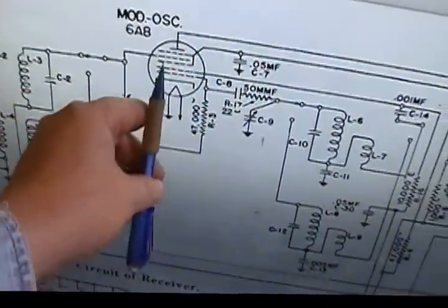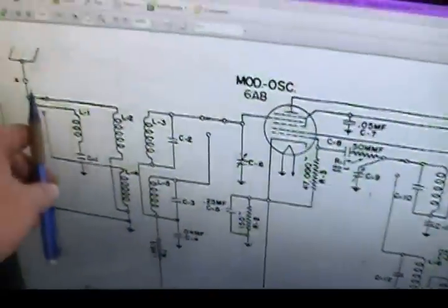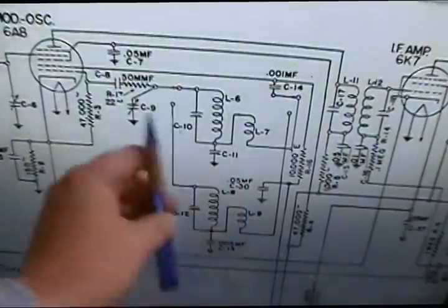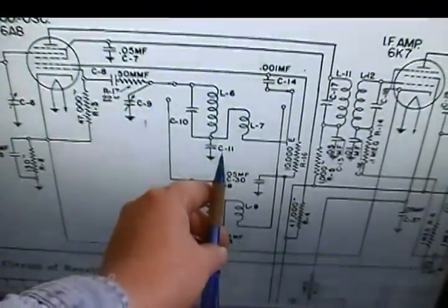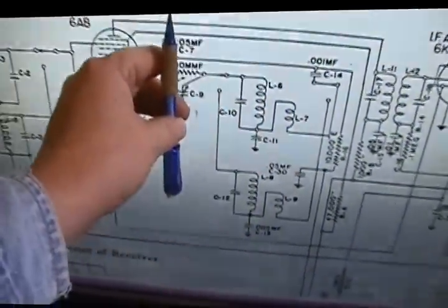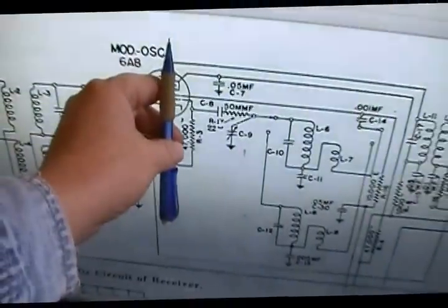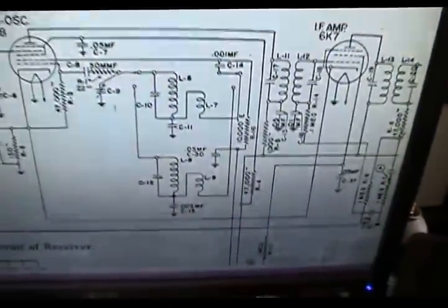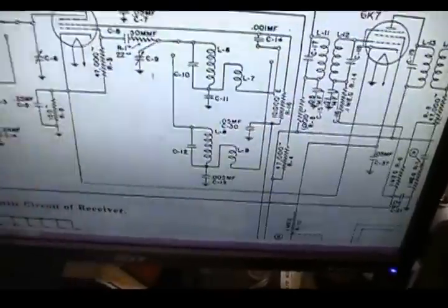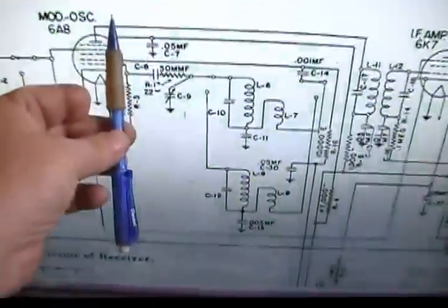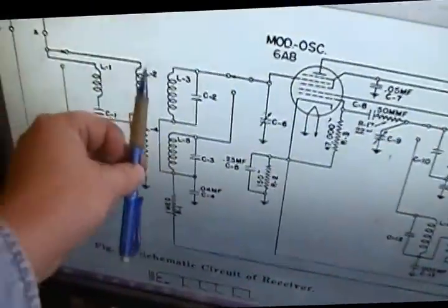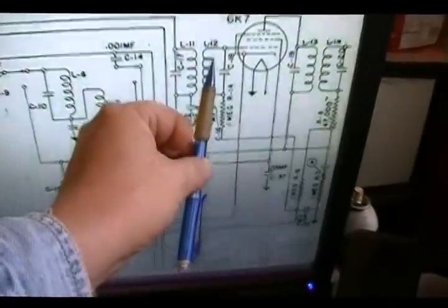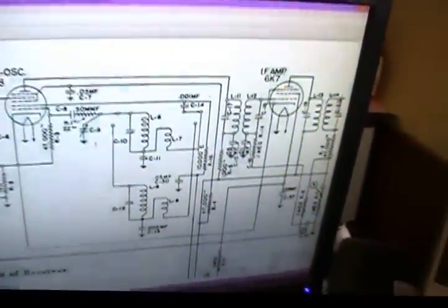What the tube does here is it pulls in a radio signal that you tune in. When you tune that radio station in, you're also, with the second part of the gang condensers, tuning the local oscillator. The two mix, and the difference of those two is the IF. Okay? There'll be 4 basic signals plus harmonics that come out. But it's the difference between the local oscillator and whatever radio frequency you're picking up that makes up the IF, and that's what will get through the IF.